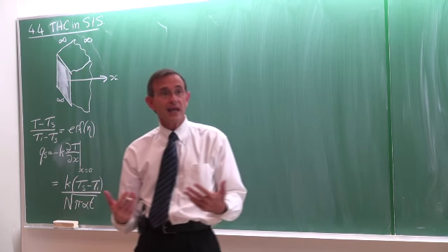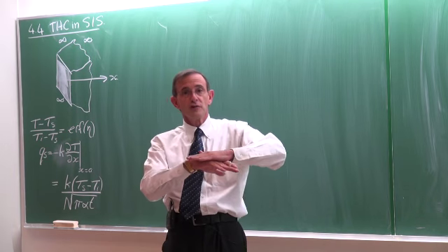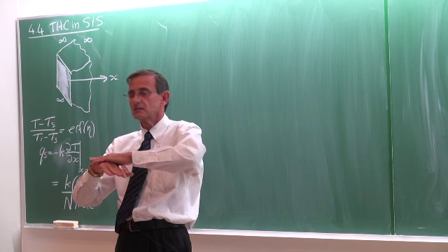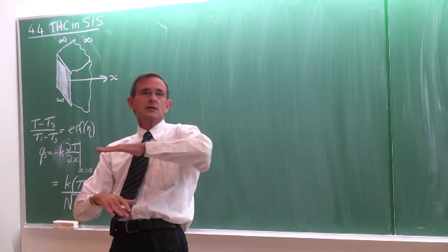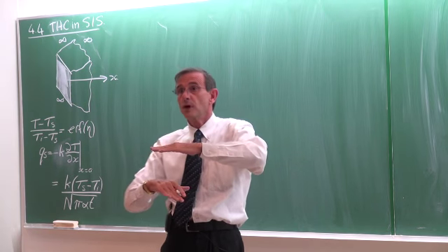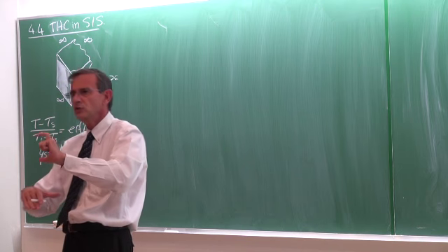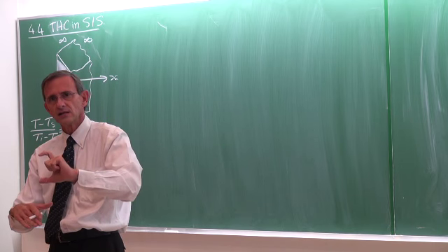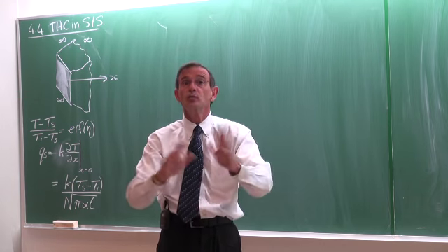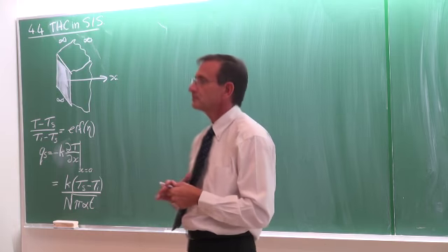And with the previous lecture, we looked at the case where the Earth's surface was suddenly at -30 for 3 months. After 3 months, the temperature at a depth of about 1.5 meters or 1.8 meters, something like that, would only reach 0 degrees Celsius. So typically at 3 meters and 4 meters, the temperature would still be constant. So the temperature of the body remains constant.